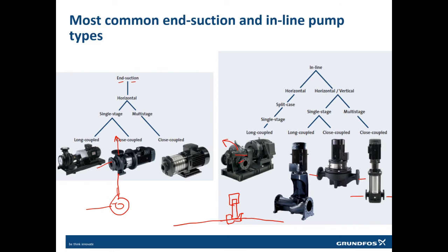You don't need to decouple the pump from the piping even. So this is the pump majority of the time used with NWC or municipalities, because it is very easy to maintain or to change the wear parts, or the parts which will wear out very fast. Then in single stage we have long coupled pumps, horizontal, long coupled pumps, vertical inline, and then we have close coupled pumps, and we have multi-stage close coupled pumps. So these are the close coupled multi-stage vertical inline pumps.